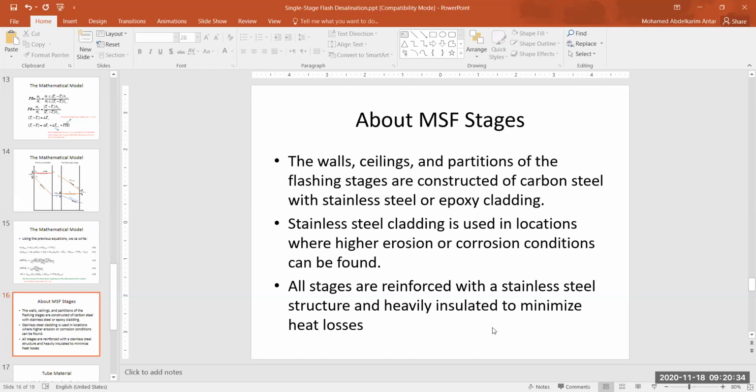The tubes are made of basically alloys. Copper nickel alloys would be there. Although for the high temperature side of the unit, you better use titanium. It's too expensive, yes, but sometimes this is something that you have to do for the high temperature side of your system, just to avoid the issue of corrosion of the tubes or scaling that would occur.